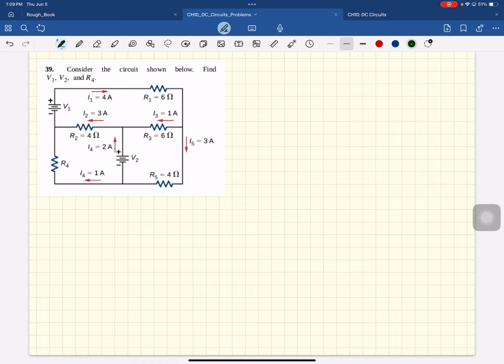A little more complicated. Again, multiple sources, multiple loops. Here's one junction, here's another junction. These are not independent junctions, but here's an independent junction, and this is independent. See, this junction is not on the other; this arm ends here. So you really have 1, 2, 3 independent junctions, so they can potentially give you three equations.